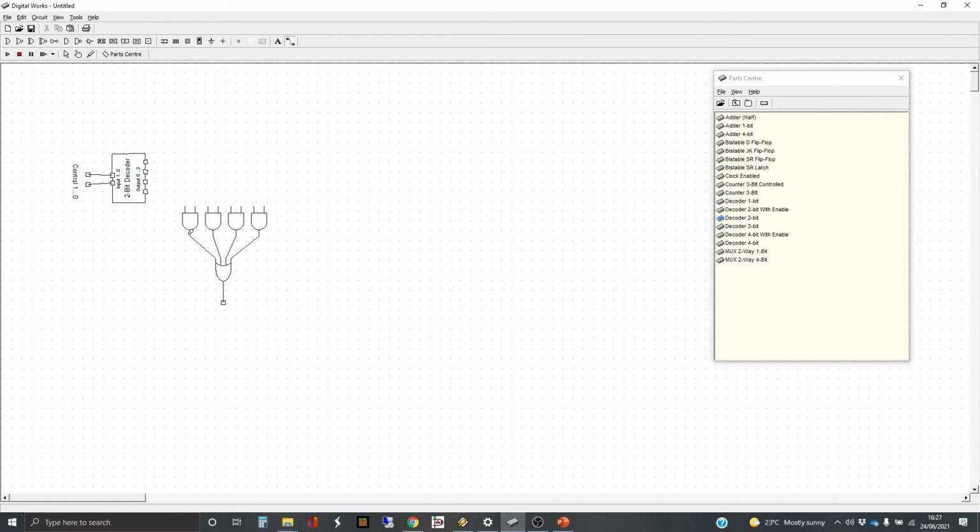You've got one AND gate for each of your inputs, and the 4 outputs from your binary decoder go into one of these each, to choose which one goes through, and then the 4 outputs from the AND gates are put through as many OR gates as you need to make sure that whichever signal has been selected gets routed through to your singular output.